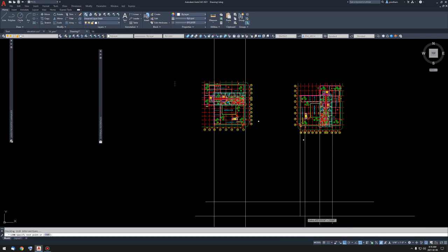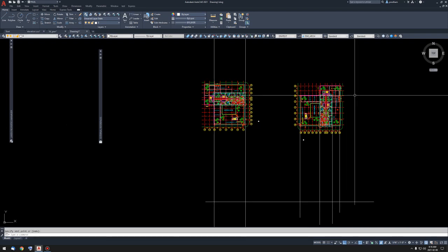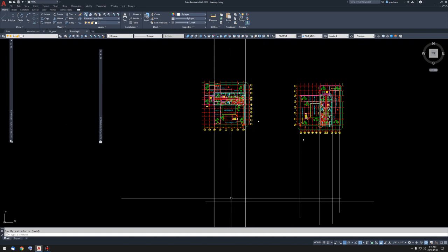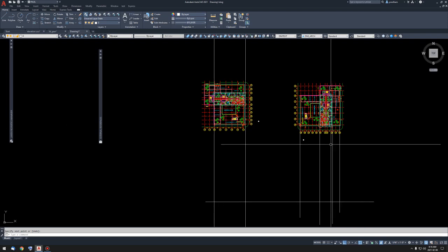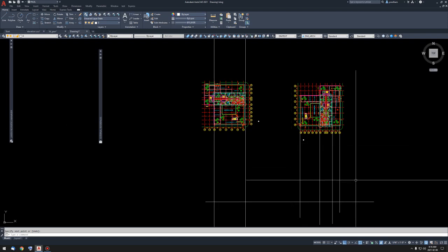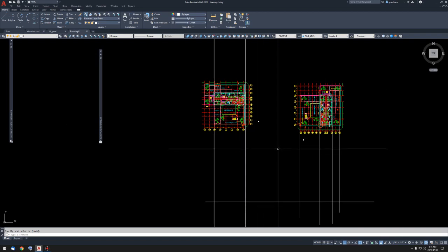And you see what we've done? We've actually made copies of the XREFs, and we've rotated them so that now when we project lines down, this is the preferred view for the north, this is the preferred view for the west, but we also have them lined up horizontally. Unlike that pinwheel system where we would have to manipulate coordinate systems.